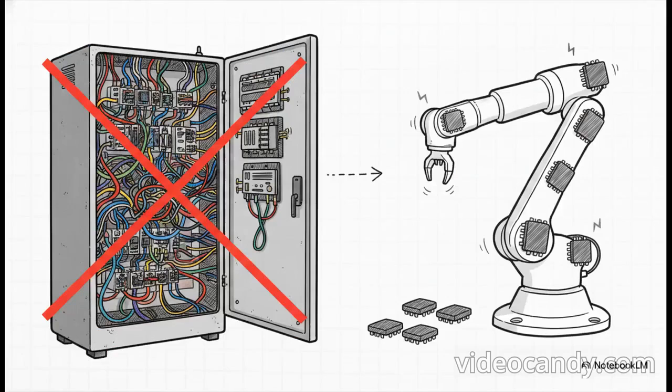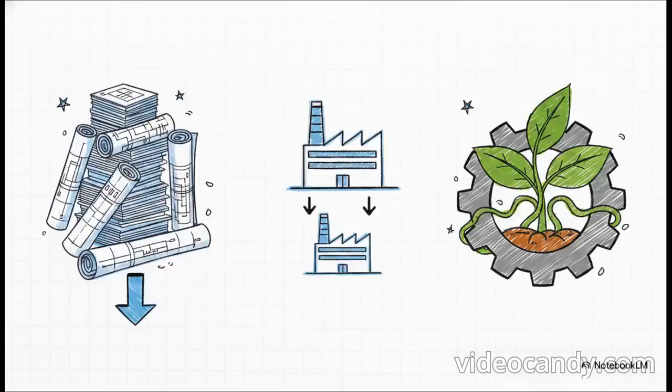And this is exactly where the MX system comes into play. It really represents the logical, ultimate conclusion of pairing EtherCAT with smart IO-Link sensors. The MX system completely replaces the traditional control cabinet with decentralized, modular intelligence. So instead of running miles of wires back to a giant metal box, taking up valuable hall space, the intelligence is distributed right onto the machine itself.